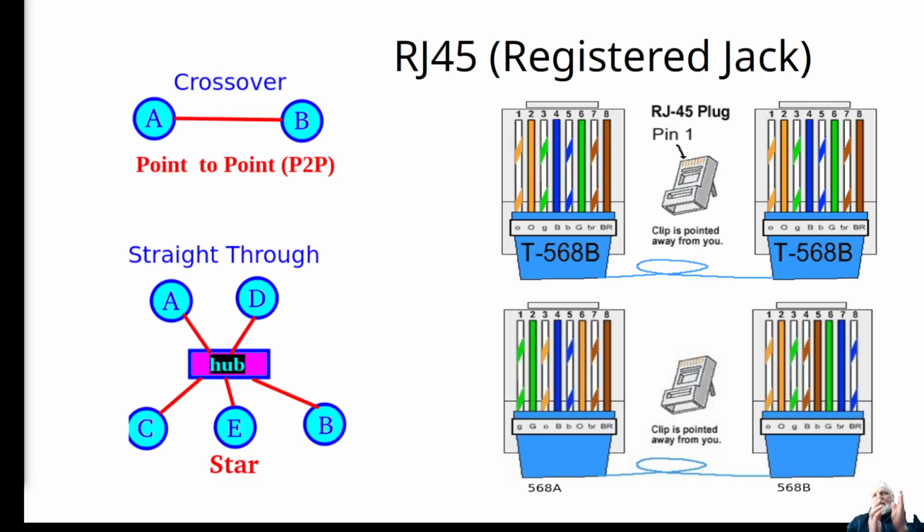And so you may need to make sure that the remote device, if you're transmitting, your transmit wires are connected to the receive wires on the other device. And that's what the crossover cable down here is doing. I've actually got these crossed in the slide here. So the crossover is crossing these and putting the receiver wires on the other end. So if you're transmitting on green, your green needs to be then going into the receive connection on the remote